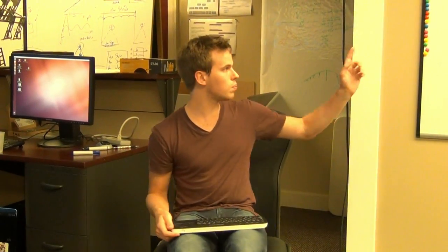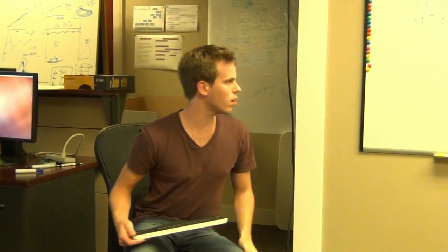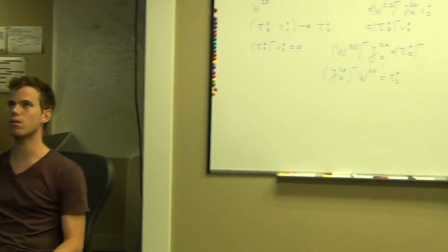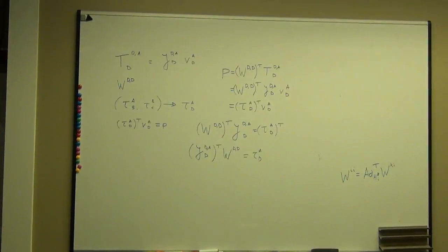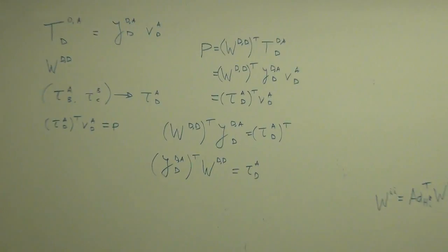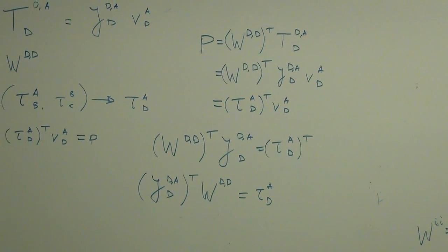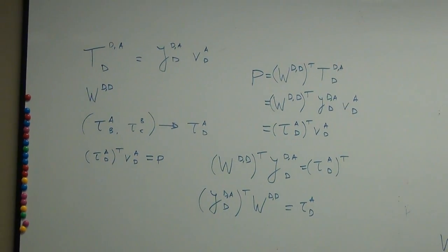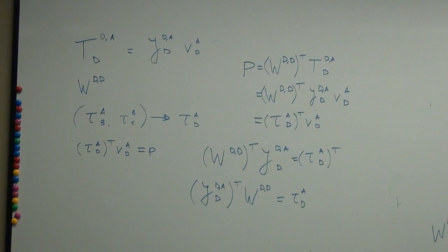So you're taking the transpose, and I think what that ends up doing is computing the joint torques that minimize, basically you're minimizing the norm of the joint torque vector. I would just make sure that the transpose is for torques and inverse is for velocities. Yeah.